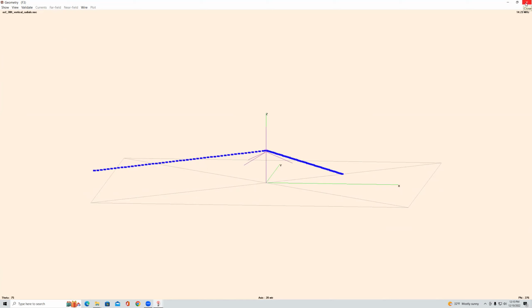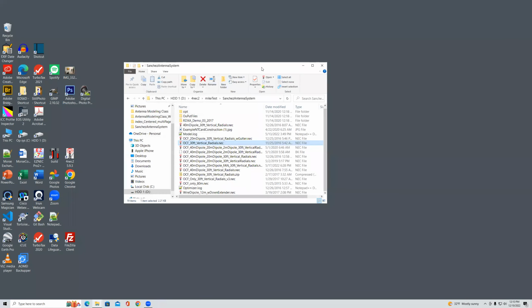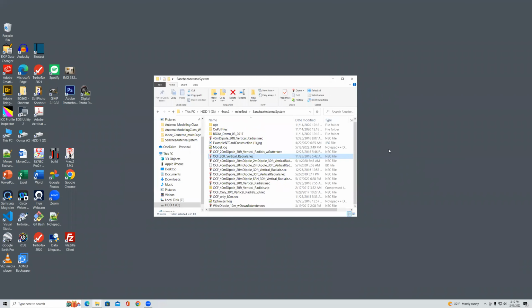Both antennas will work, and both will get you on the air, and you will make contacts, but eventually it comes down to, what's your big goal? What do you want to get out of it? If it is DX, those rare DX expeditions that pop up every now and then, there's a pretty good chance that a vertical will get you there quicker than a dipole.